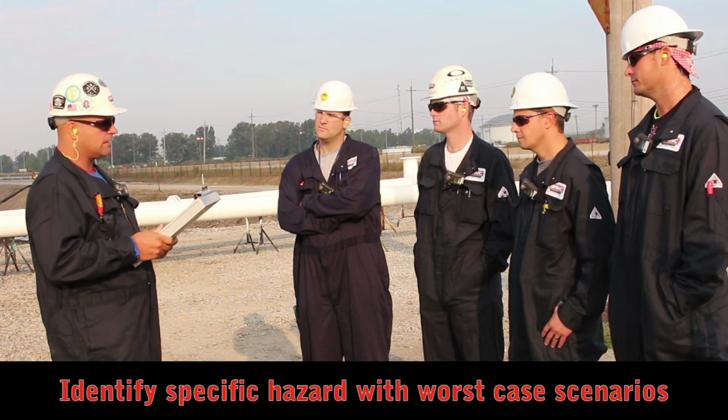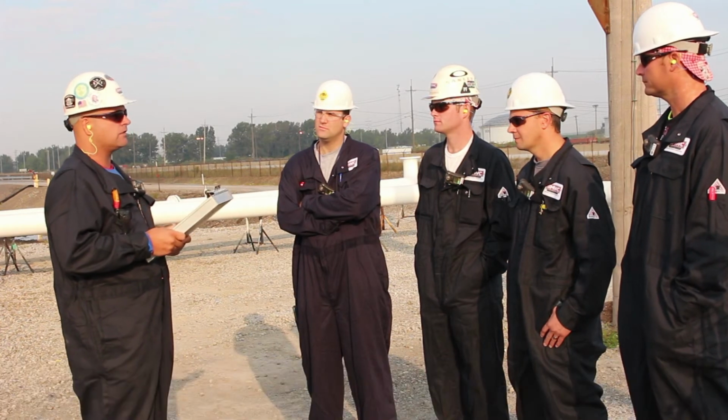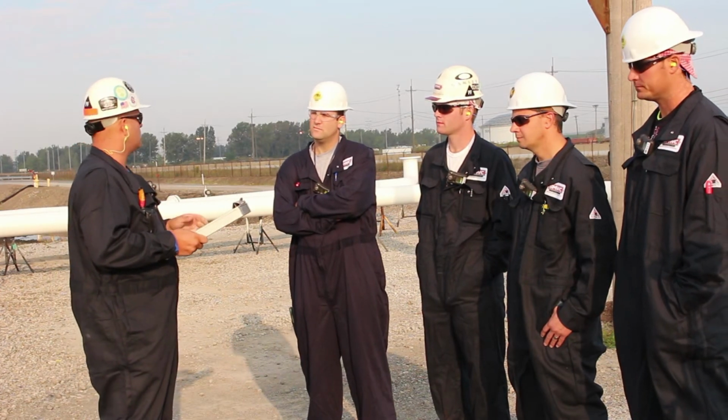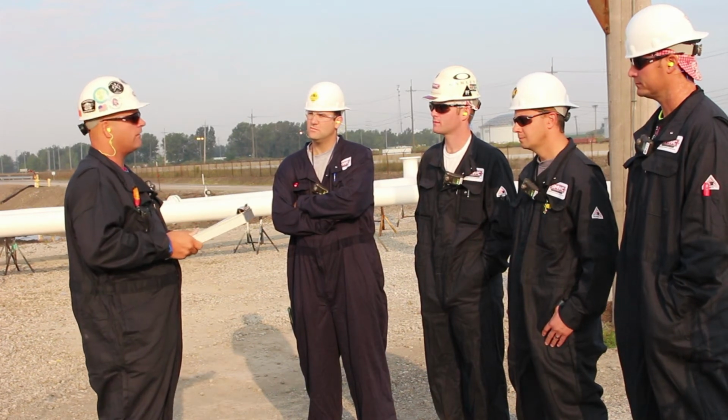Can anybody give me 2 examples of how somebody can get killed today? H2S. H2S, there's gases everywhere. Falling loads. Falling loads, correct. So stay out of the line of fire, and for the H2S, in the event our monitors do go off, we walk crosswind and make sure everybody knows, okay?